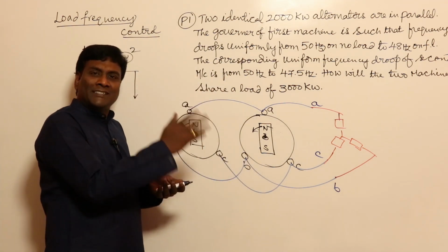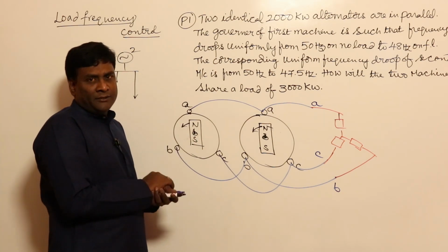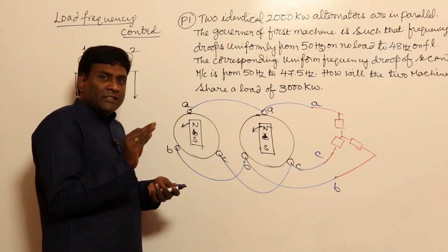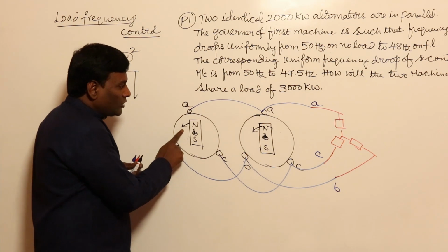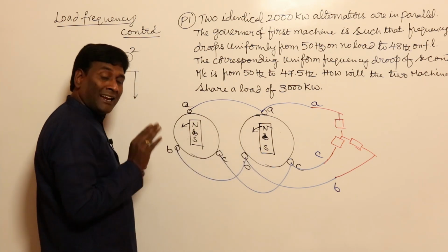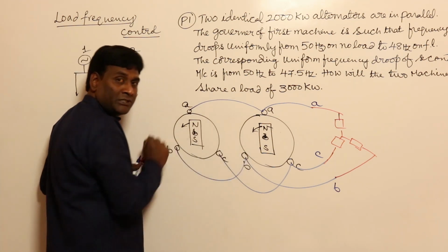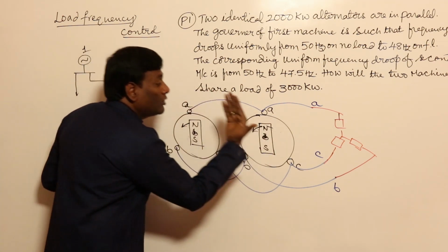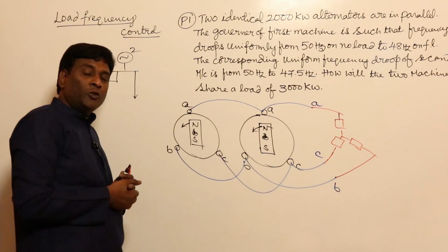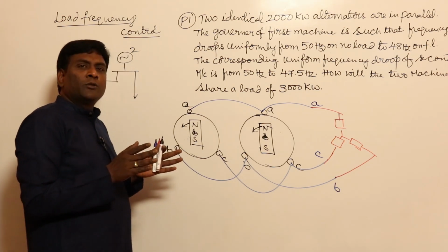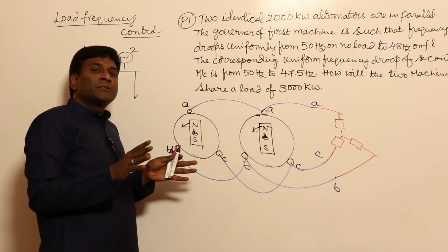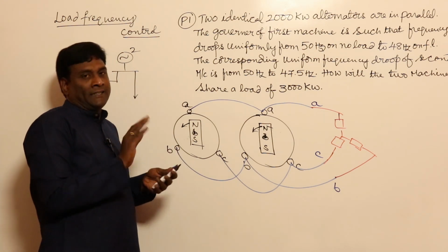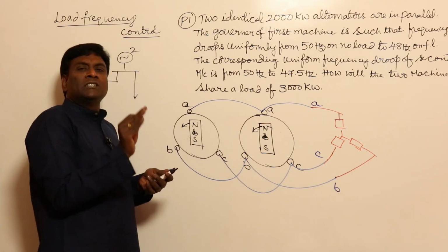The point here is very simple. Of course, a lot of discussion is there, but for the time being it is enough. The logic is very simple. The direction of rotation should be the same, the speed of rotation should be the same, and the position of rotors with respect to one another should be the same. Because of that, mechanically all synchronous machines are virtually coupled. Anyway, the conclusion is very simple.